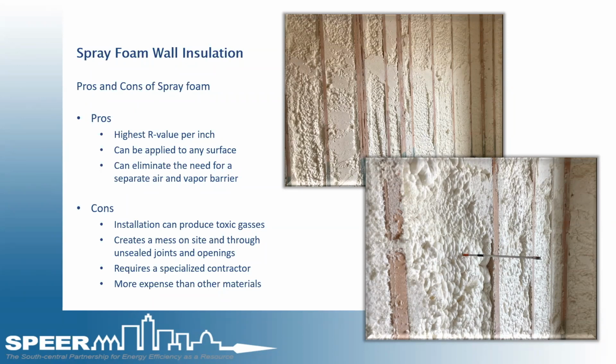That's becoming less and less of an issue down the road, because those insulators that do batts have now learned how to use foam. They've got a foam rig, they know how to do it. But if it's not installed correctly, there's a chance that the installers are trying to save labor and time. So if you spray foam correctly and you fully fill the cavity, you got to go back and shave off the cavity, and that way it's got full depth insulation on all of it.